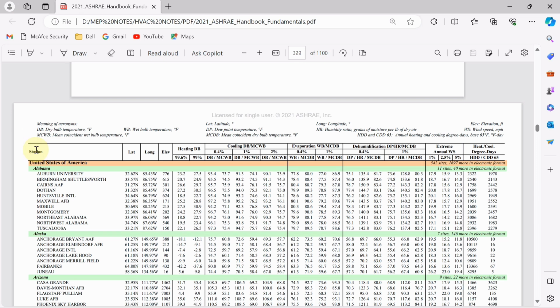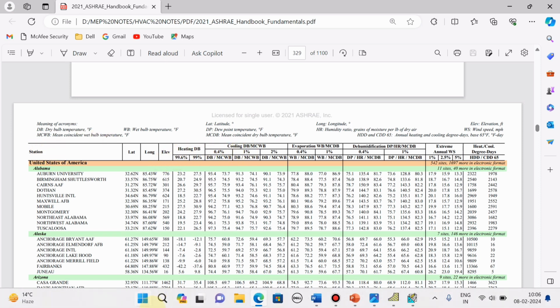I think all of you know why we are using this climatic design. Simply, the climatic design information that I am taking from here includes dry bulb temperature, wet bulb temperature, relative humidity, solar radiation, wind speed, and outdoor air condition, because this data is used to determine the thermal characteristics of the building envelopes, the internal heat gain from occupants and equipment, and the required heating or cooling capacity of the HVAC system.